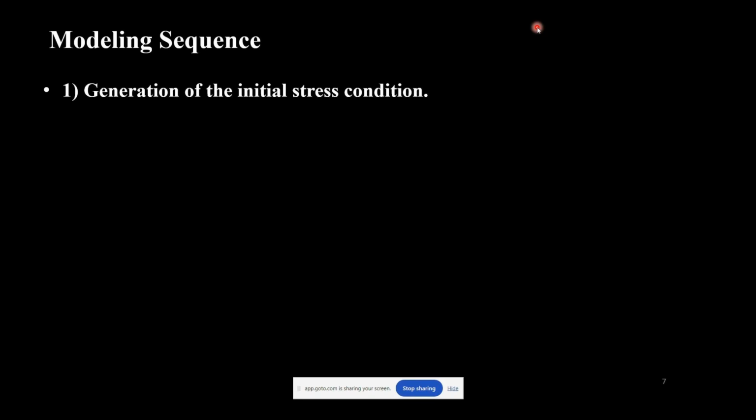So it means that the vertical stress is equal to the horizontal stress. We have no shear stress in the rock salt initially. And this is a reasonable assumption because we expect that rock salt, because of its viscous behavior, should have an isotropic stress state. This is what is expected.